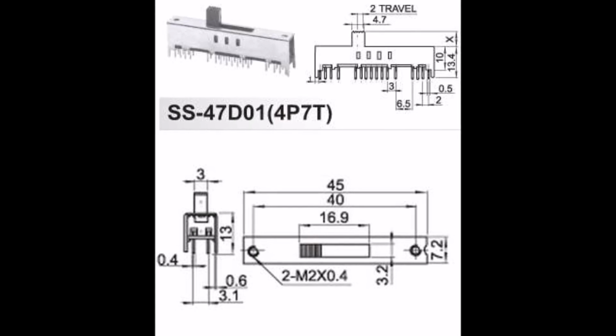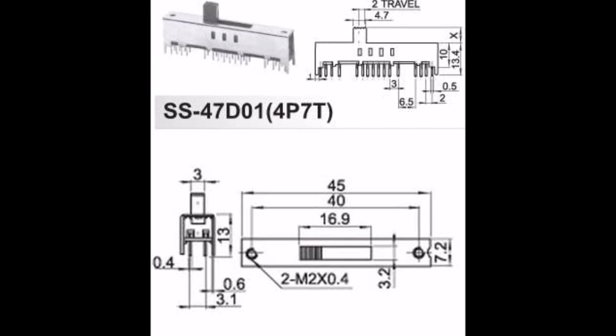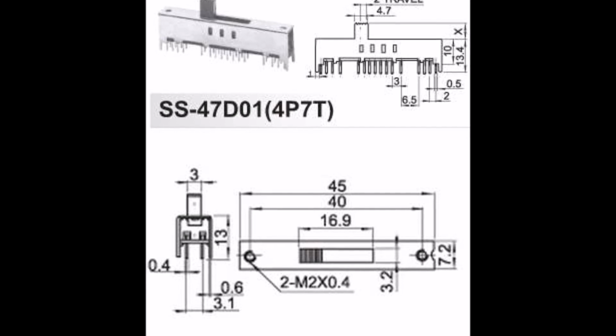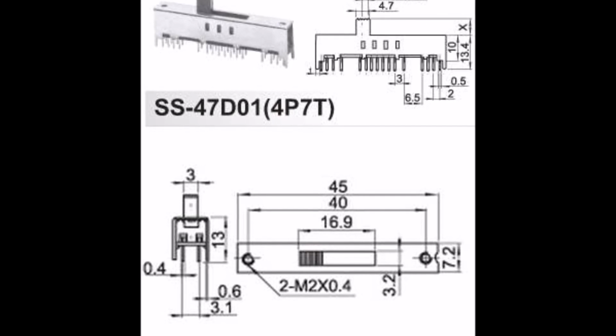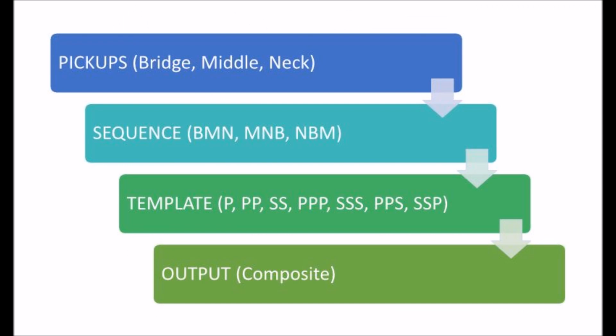The 4P7T and 6P3T are large profile switches, which makes them a challenge to layout, and switching between the different positions may also require some dexterity. In exchange for some redundancy and dead sound combinations, the template selector can be limited to selected patterns, but the phase switches must have a center-off position. The cost to build it is reasonably flexible, and depending on the type and quality of the switches to be used, this system can be quite cheap, or very expensive to build.